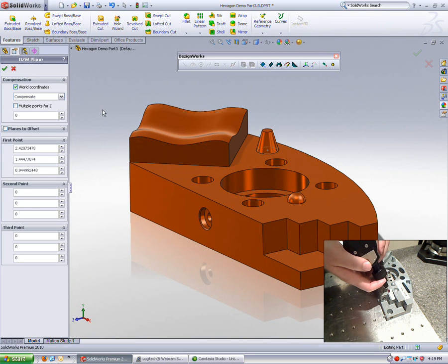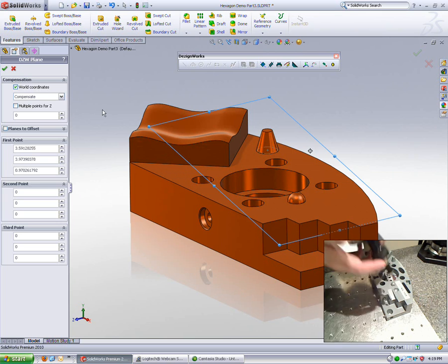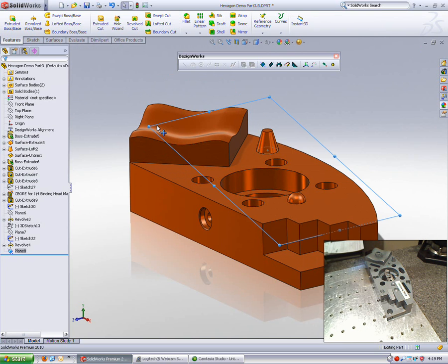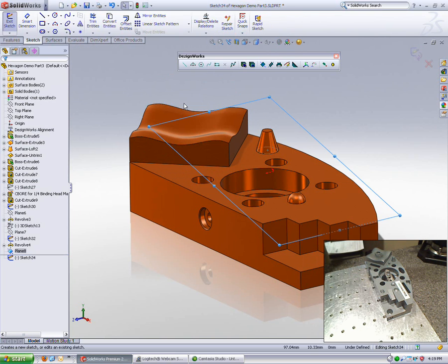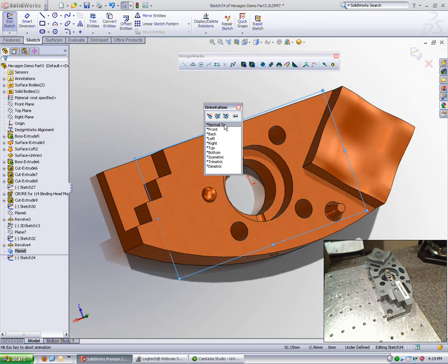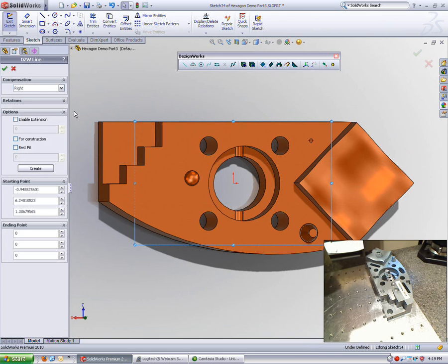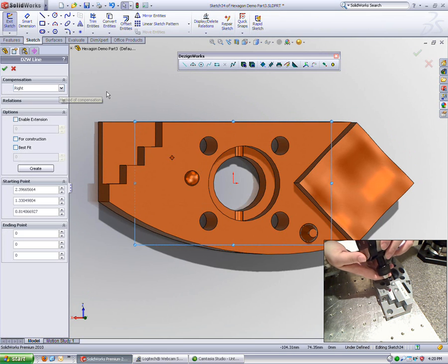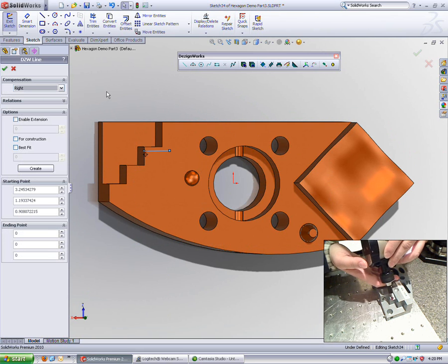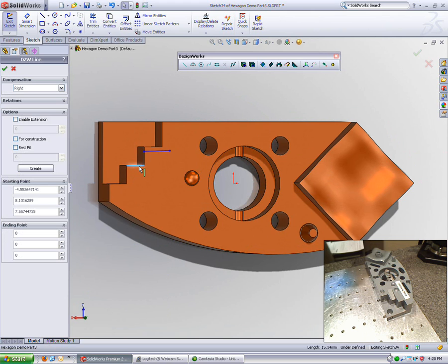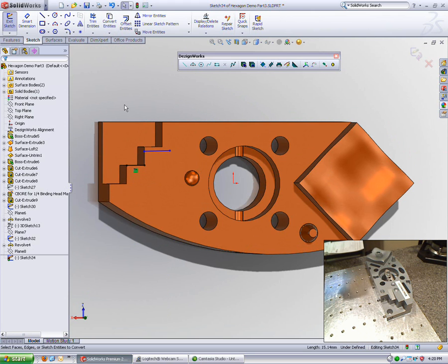The last thing we're going to do is actually create this angled cut, and we're going to do that by creating a Dezignworks plane. So we can create a plane inside of SolidWorks using Dezignworks tools, which will actually allow us to take 3 points on the surface and get that angled surface inside of there. So we know it's flat for one, and we know it's oriented properly because we've created it with Dezignworks. It would be very difficult to get that angled surface that is just positioned somewhere in space without having the use of the Dezignworks tool as we're reverse engineering this particular part.